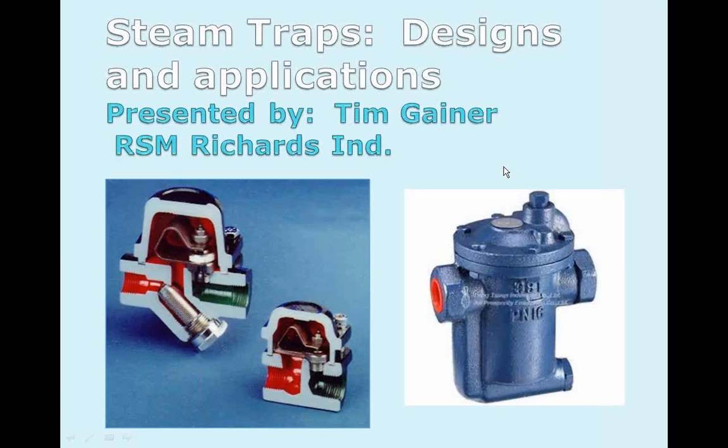And they look closely at, hey, which technologies use steam, which ones don't. And you look at total cost of ownership. Okay, maybe a float and thermostatic or a bimetal is more expensive than a disc trap, but I have a strainer, I have a check valve in there, so I don't have to buy or pipe in those components.